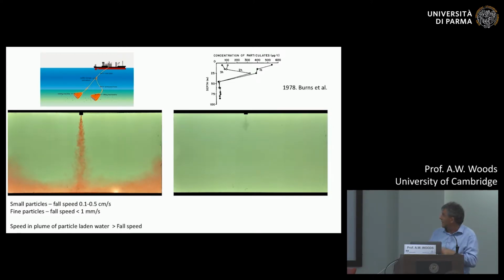But if we do this in a stratified tank, a stratified ambient, of course what happens is, as this shallow water is entrained in the plume, the water here, which is fresh, moving down into the denser fluid, actually compensates for the salty water being supplied at the source, and so the flow doesn't run all the way to the base, but it intrudes at some height when the total buoyancy is depleted. So essentially, if we move through a continuously stratified zone, then the plume is arrested rather than moving to the base of the tank.